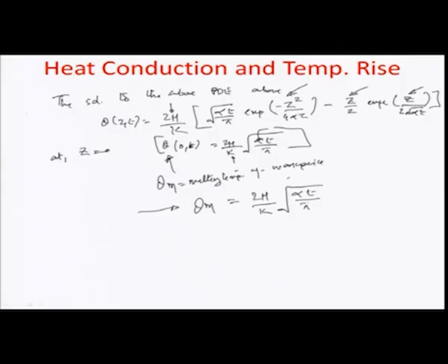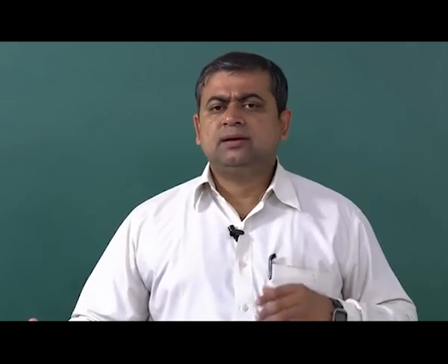In other words, we know theta m from properties of the material, and we know the beam power that we are using. In fact, it is very critical to estimate the beam power considering all the reflective losses from the surface, because most of the power is lost from this coupling mode by the essential evil called reflection, particularly for smooth and shiny surfaces.